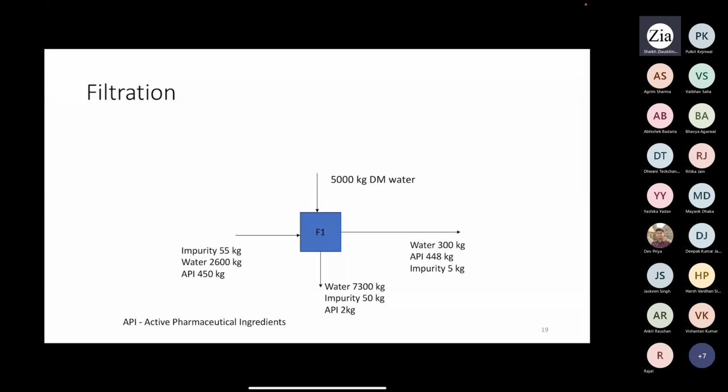But when you do this mass balance calculation, you will see the efficiency of each and every unit. Like if your target is to get 80% separation of a certain component present in the raw material, and in one particular filter system you could get maximum 30% efficiency, then it will allow you to design how many such units are required and what kind of arrangement would be there to get better efficiency or better utilization, whether in upstream or in downstream operation.